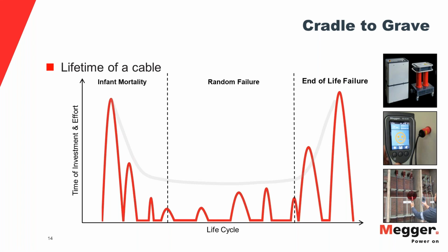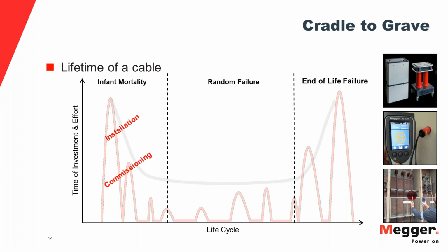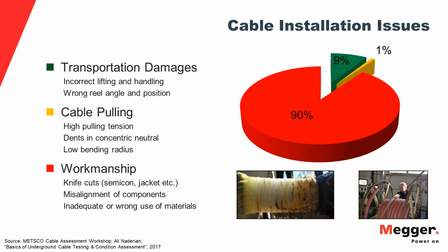In this case, PD testing predominantly. And then, of course, in the early fallout there will be gross defects that will appear, hopefully during acceptance testing, installation and commissioning testing. Then here, this is just the area of maintenance. You will find hopefully just some smaller defects, and end of life will be when more failures show themselves. And now to the point where PD testing is most effective.